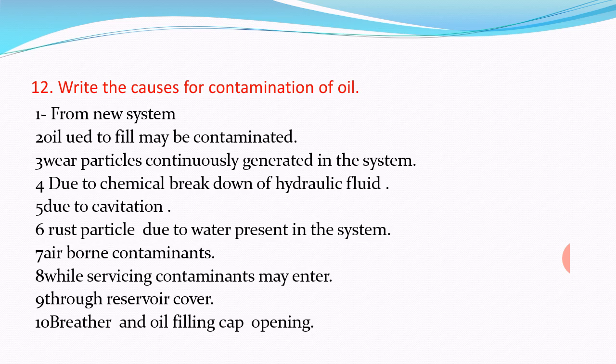The operator is not taking care of the dust particles and metal particles. Then ninth one, through the reservoir cover. The reservoir cover has some clearances, or it will have a vent, and through that also contaminants will enter. The breather and oil filling cap also may have some openings through which contaminants may enter. So those are the causes.